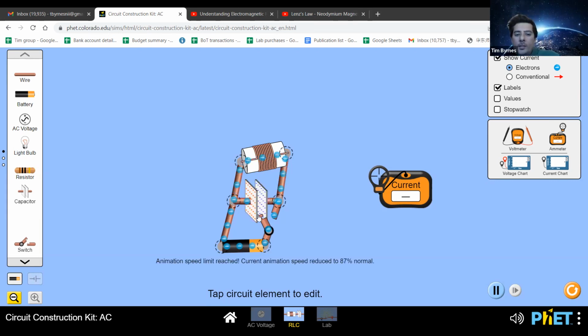But at some point the capacitor stops it, and then the capacitor tries to get rid of its charge, and the inductor is trying to stop the change in the current. So this cycle just continues on forever and ever. An LC circuit, or tank circuit, has this natural oscillation frequency for the electrical circuit.